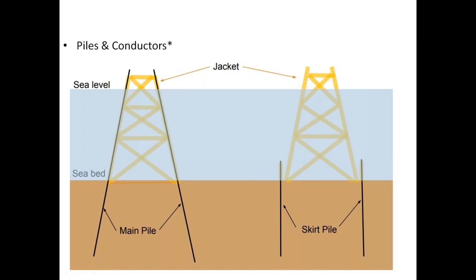Because of its unique properties, they have less drag and inertia coefficients, they have equal properties all around, and they are very torsionally rigid. Having all these things in mind, we generally go for circular hollow sections, and the piles will be inserted inside that hollow region. That means inside the circular hollow, we will insert one more tubular. This is a bigger CHS, and this black color one is a smaller CHS, that will be inserted inside the jacket leg, and this is the seabed, and that will be driven